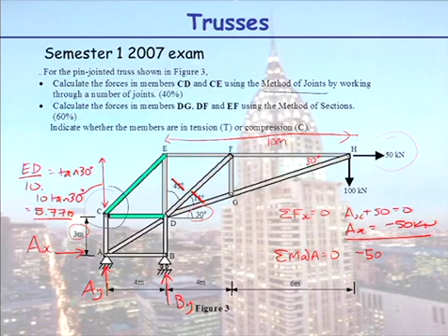So now when we take moments here, we have 50 horizontal force times the vertical distance from A. So that would be multiplied by our height of 3 plus 5.77. I put a negative sign in it because it's going clockwise. And then you would also have your 100 kilonewton and the perpendicular distance from A. The full distance is 4 plus 6 times 14.